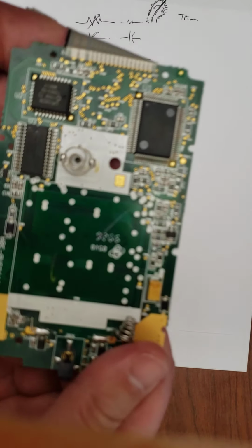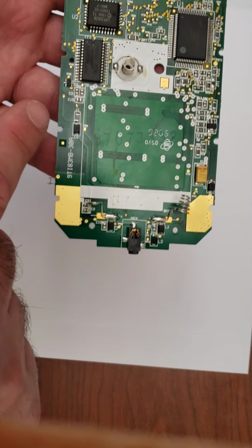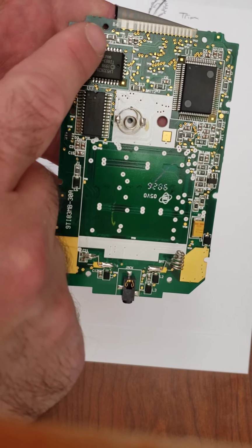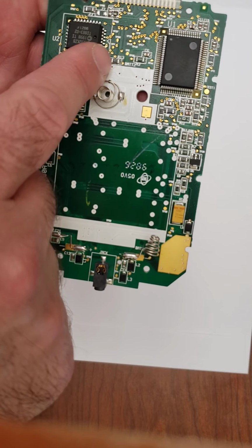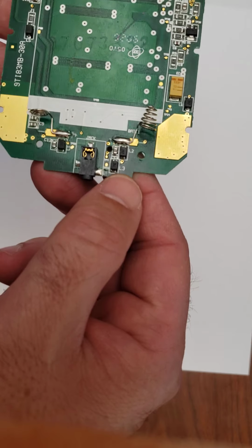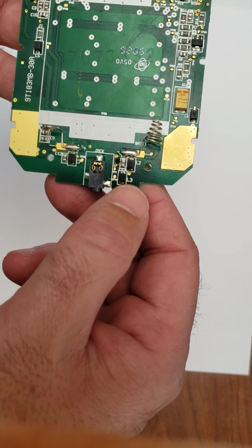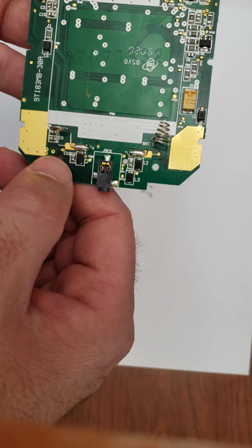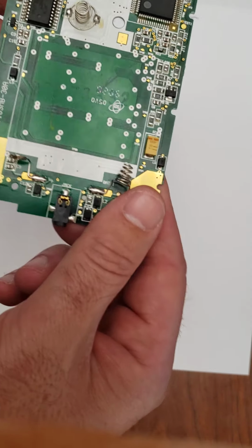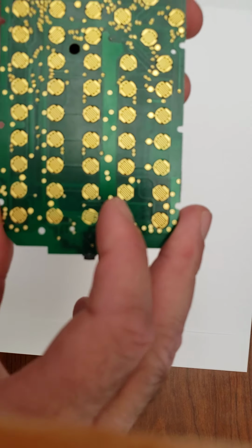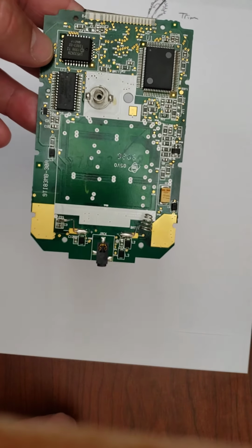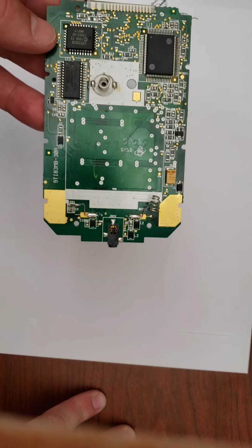Now, if we flip it over, a couple things to notice here. You can see some of these things have C, some of them have U's for a circuit, but there's R's and L's for inductor. Say L3 would be for an inductor, power jack, and the C12 would be some sort of capacitor. Also notice that none of these components go through to the other side. So unlike the stuff you're building on your breadboard, these things are all just mounted on one surface, and that's called surface mount.